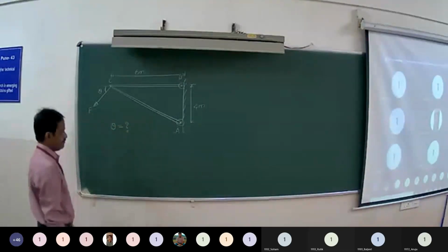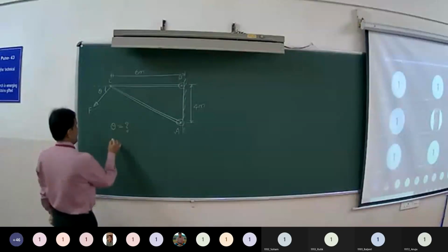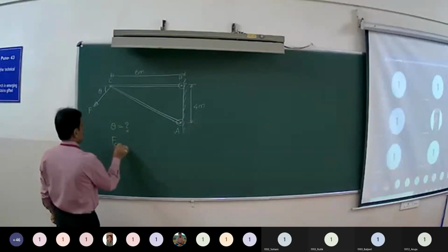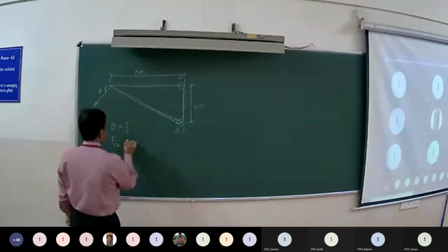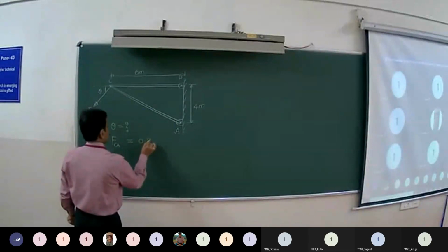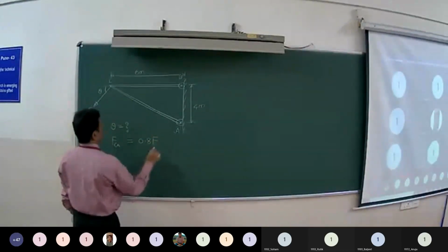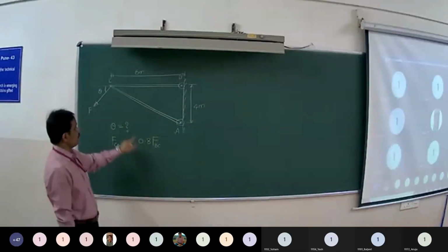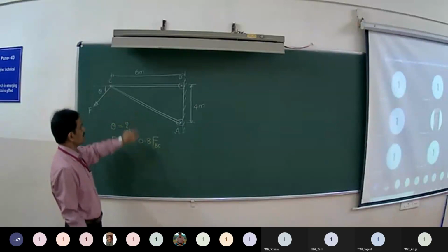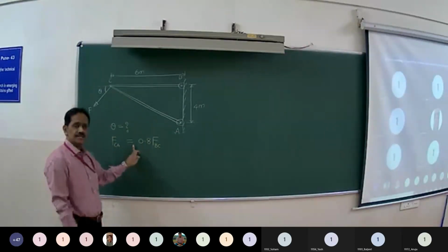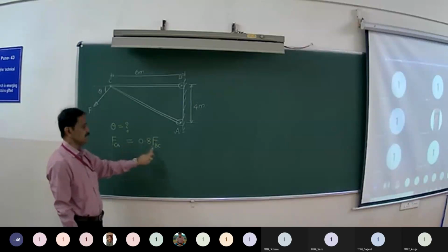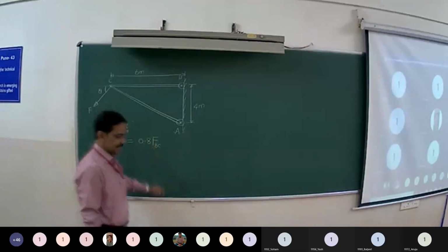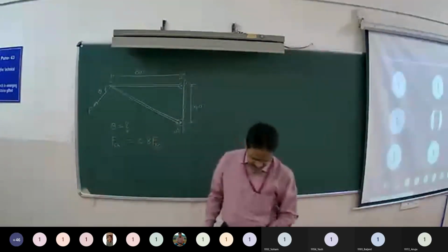for the condition that the component of force along CA does not exceed 80% of the component along BC. It is said that the component along CA does not exceed 80% of BC. Means what is the limiting condition? At the most, it can be equal to 80% of the component along BC. Right? So this is the given condition.